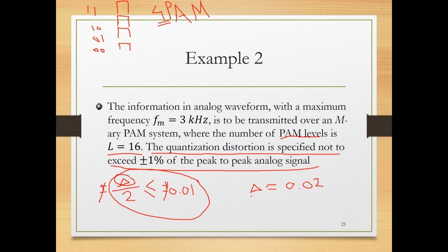Yes? What's delta now? Delta is M max minus M min over L. Now don't confuse L. Here L is for the number of levels. We will call the number of levels there K or something else. Or we change this, we put K or M here, and here we keep it, the number of levels for the quantization, we keep them L. So here delta is equal